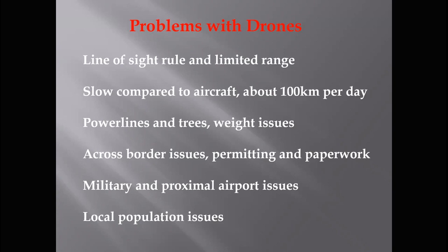But it is a pain, particularly if you're in a flat area. Say you're in Botswana, you can only really see that drone for, if you're lucky, a couple of 100 meters at a time. So then you have to build a platform in the area, or it's just not realistic to fly 500 meters at a time. You want to try and fly blocks with a drone of 2 kilometers by 1 kilometer wide and then merge all the blocks together, something like that.